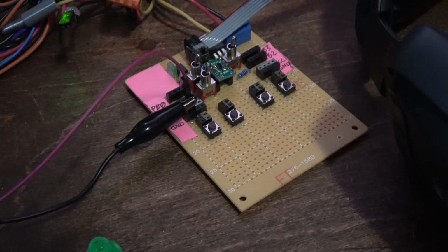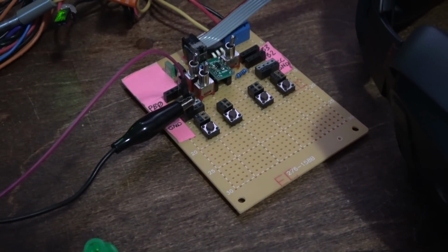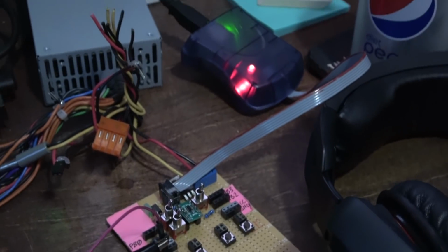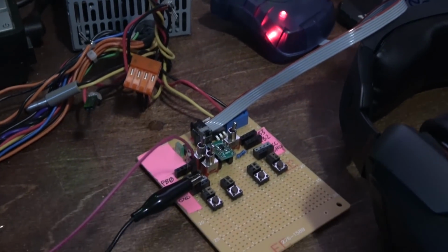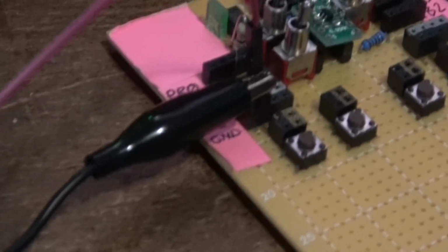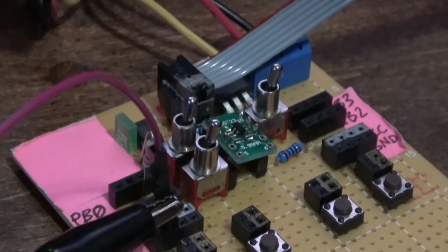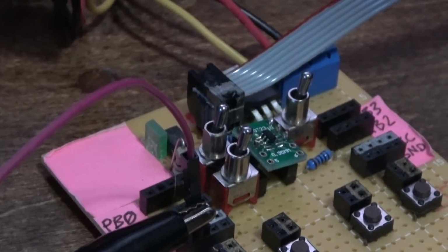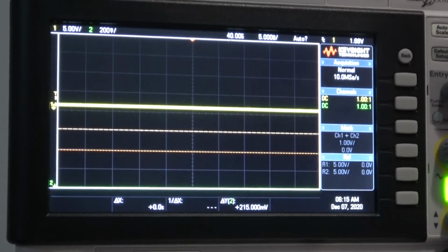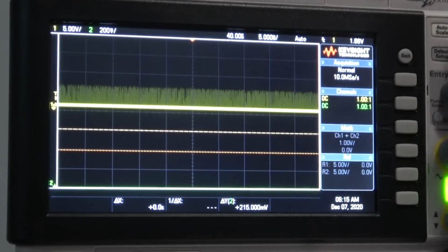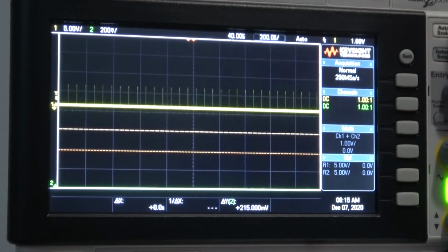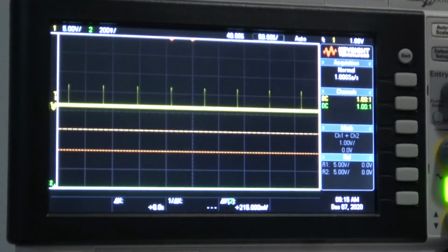And we're using the same rig as before, the high voltage programmer for ATtiny, and we're driving it with an AVR ISP mkII. But now we can try it out. And I've got my toggle switches, so when you move the switches to the left, that allows you to output the application, and when you move them to the right, that sets them up for programming mode. Suppose if I hooked it up to my scope, that would help. Oh, there's something. Okay, look at that. All right, let's get the measurement.